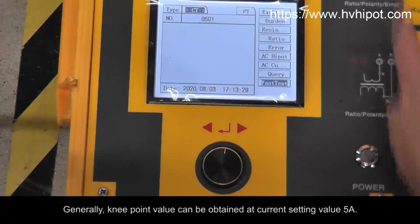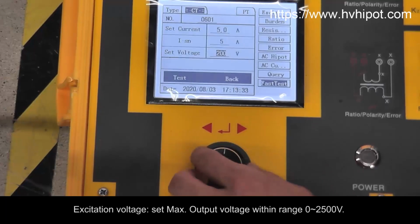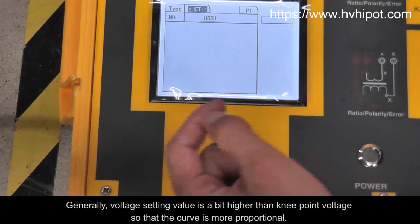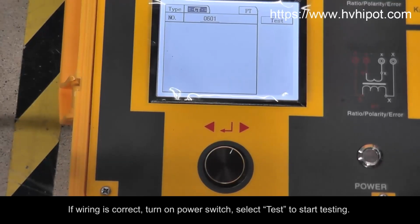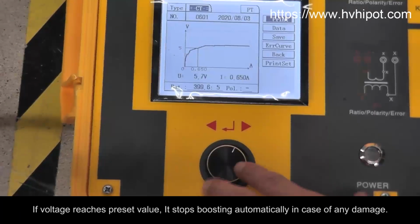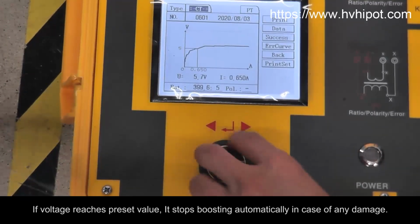Generally, knee point value can be obtained at current setting value 5 amperes. Excitation voltage, set max. output voltage within range 0 to 2500 volts. Generally, voltage setting value is a bit higher than knee point voltage so that the curve is more proportional. If wiring is correct, turn on power switch, select Test to start testing. If voltage is set too high, curve is closer to y-axis, otherwise curve is closer to x-axis. If voltage reaches preset value, it stops boosting automatically in case of any damage.